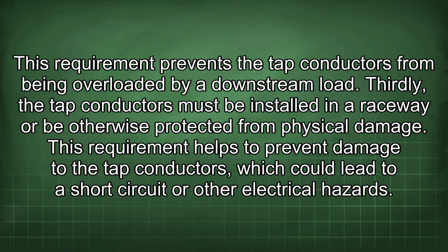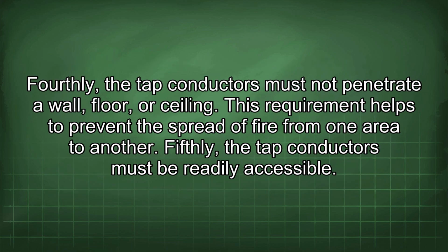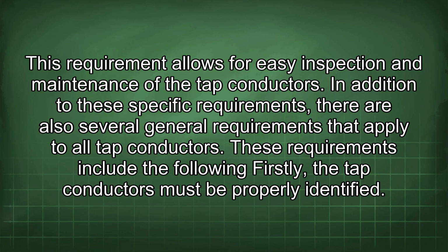Thirdly, the tap conductors must be installed in a raceway or be otherwise protected from physical damage. This requirement helps to prevent damage to the tap conductors, which could lead to a short circuit or other electrical hazards. Fourthly, the tap conductors must not penetrate a wall, floor, or ceiling. This requirement helps to prevent the spread of fire from one area to another. Fifthly, the tap conductors must be readily accessible. This requirement allows for easy inspection and maintenance of the tap conductors.